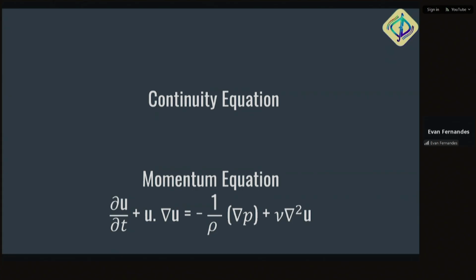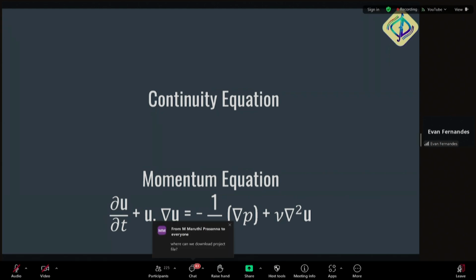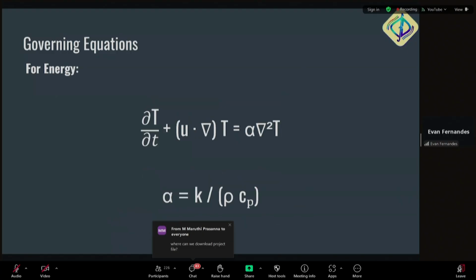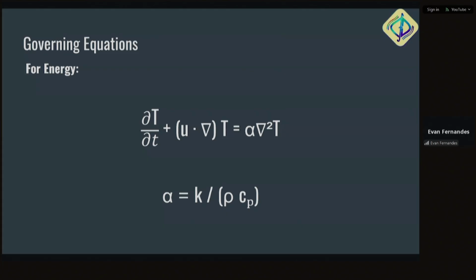For this reason, you would have to first solve the continuity of flow equations, that is your Navier-Stokes equations. So you would have your continuity equation and your momentum equation. Additionally, since we are using the scalar transport form, that particular solver solves the energy equation as well.